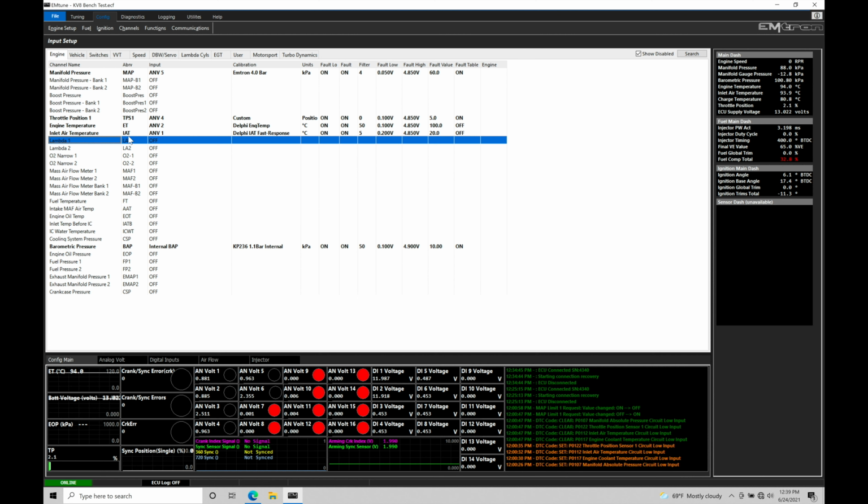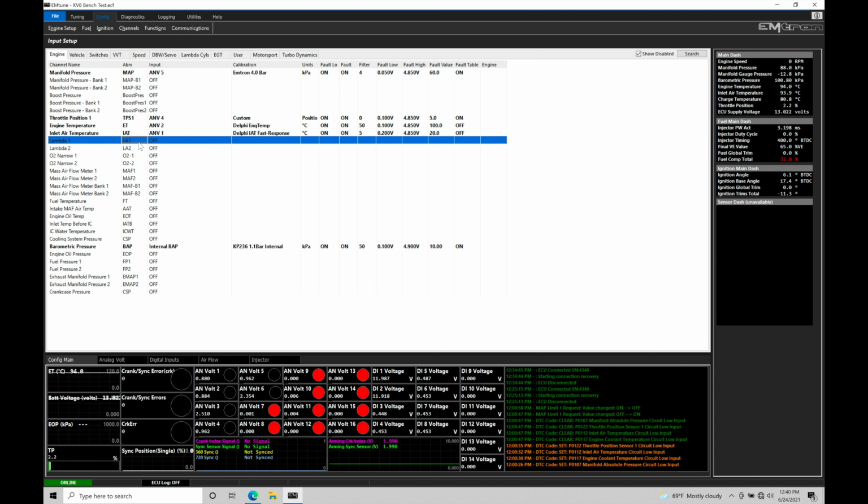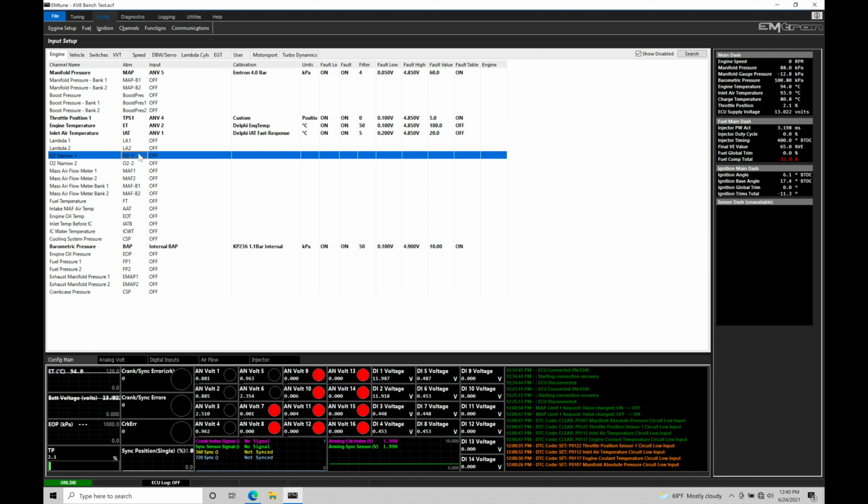Now, we're going to be taking a look first at setting up a Lambda sensor. We have either the Lambda sensor or a narrowband sensor. In this case, there's almost no reason to not run a Lambda sensor. The narrowband sensors will provide some type of feedback at stoichiometric, or where the petrol fuel is 14.7 to 1, that could be used for closed loop operation. We'll get into all of that in separate training tutorials. But the Lambda sensor will be a wideband, so it can read all the way from 10 to approximately 20 to 1 air fuel, whereas the narrowband is really focused on just that stoichiometric, or 14.7 to 1, again just talking about the petrol gas air fuel scale.